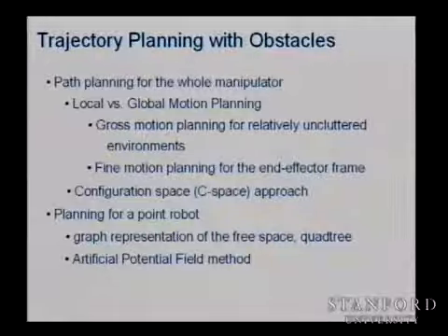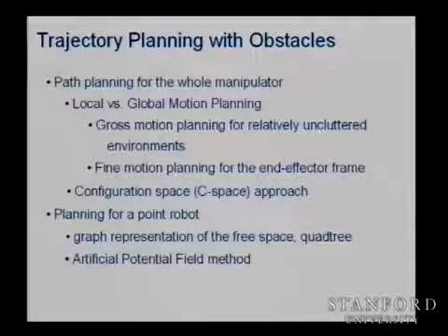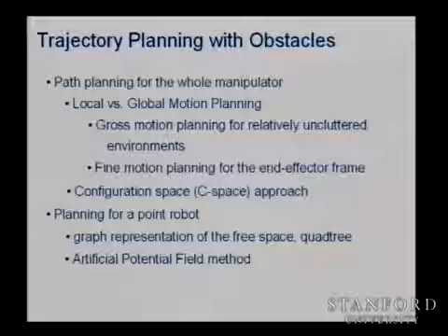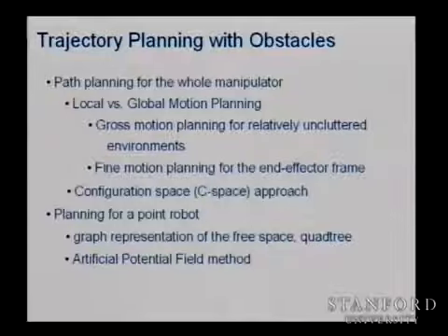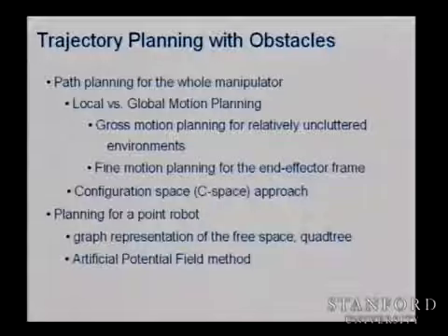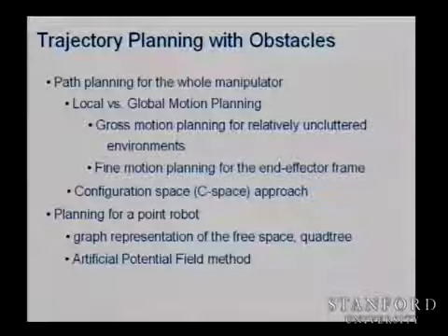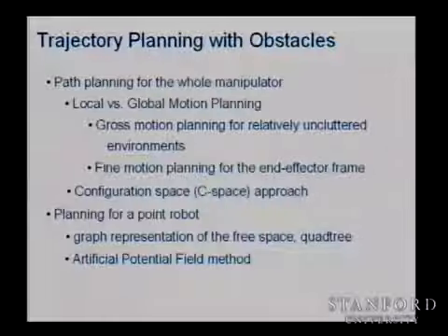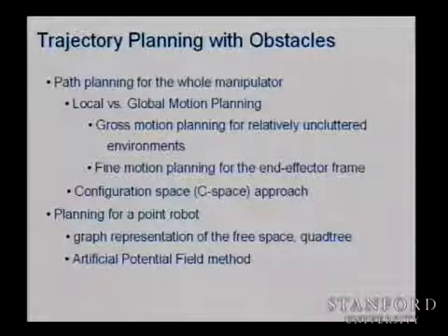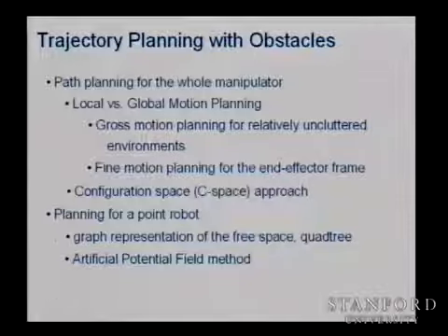And you can use things like the artificial potential method, where as you go closer to an obstacle, you have a force repulsing you from the obstacle, and as you approach the goal, you have a force attracting you to the goal, and based on that, you can build an artificial potential field, which is, by the way, what Osama did way back in his thesis. It was very revolutionary work at that time. And then you get into all kinds of interesting things like local minima, global minima, maxima, etc. So it's a fun thing.